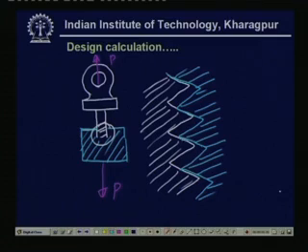This clearance will also determine the total area of contact, and this is the area of contact over which the bearing pressure will act. But this is very complicated for analysis, so we have to make a very rough estimate. Why rough? Because we can provide an adequate factor of safety such that the bolt doesn't fail even if we have a very rough estimate.